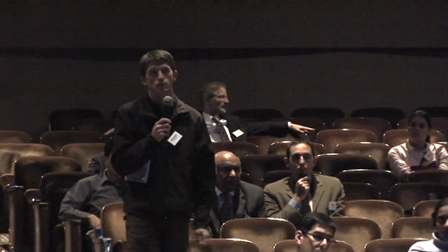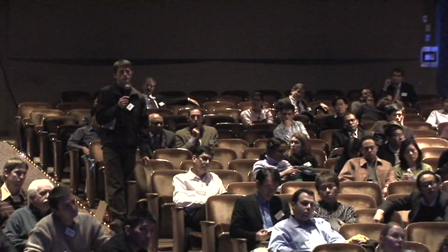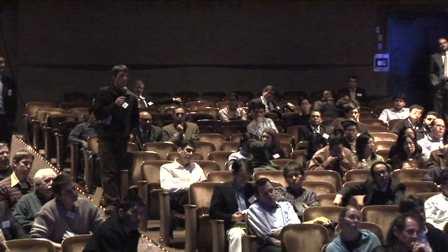Any questions? I guess my question is, how do you get the modal analysis output from Perform? So why do you need it? The mode shapes to calculate the force pattern. I know Perform will do it for you in doing a pushover analysis. Right. But if you're doing a modal pushover analysis, you need, for each mode that you're doing the pushover for, the torsional moment as well as forces in both x and y directions. Oh, so you want to apply the modal forces but give them some eccentricity, huh? Yeah, essentially, for the modal pushover procedure.